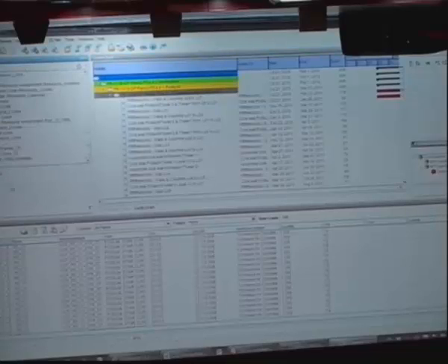And different things are going to happen. You're going to see a Gantt chart is created for you automatically, showing the WBS up to level 5. You also have all the relations that we just created manually will be created for you automatically, showing the activities, the resources, the activity relationship between successors and predecessors, the calendars. Any information that exists in the schedule, it comes here, it's created as a data structure and displayed in the Gantt chart. What we want to do is we want to link it to the 3D model.